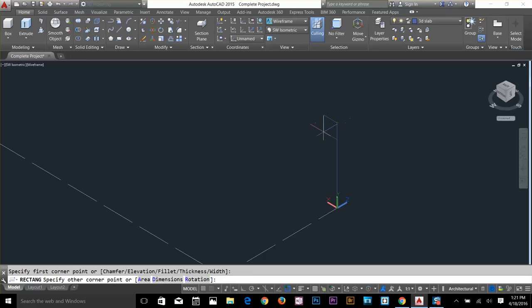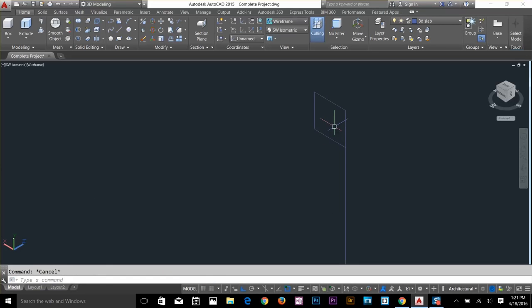So I'm going to draw a rectangle here of dimension 4.5 by 4.5, done. Alright, so that's done, and I'm going to use the fillet command, radius about 1 inch. That's fine, and I'm going to give another radius about here.